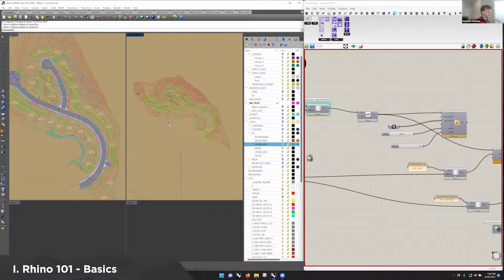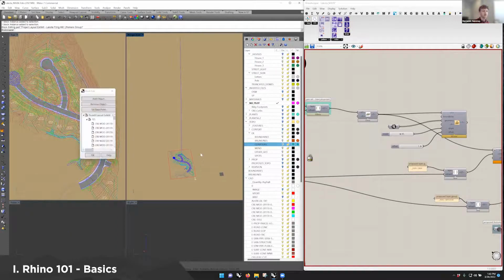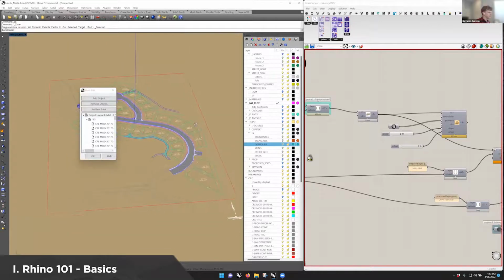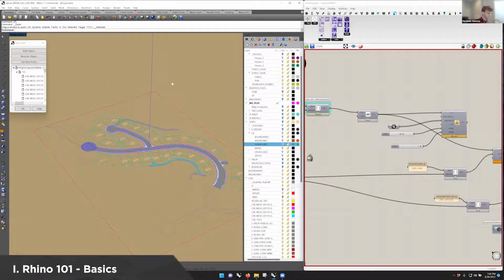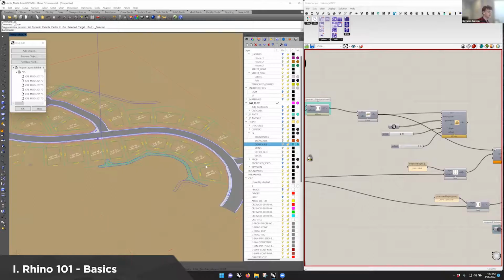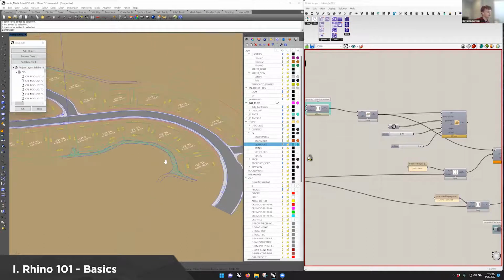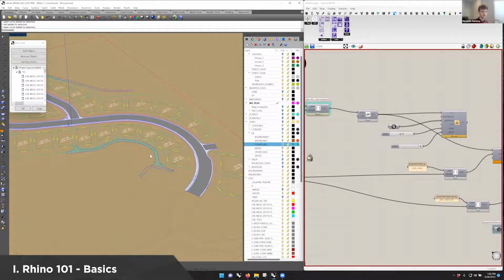Okay, so a couple more things to remember, especially when you start dealing with the plan down below. This will be a little more apparent once we talk more about the collage and the areas, but I'll go down here so you can see a little closer. Oftentimes when surveys or line work come in from some source, GIS or otherwise, the line work is not always perfectly touching or matching. And when you start creating surfaces and splitting them into different areas, whether or not the lines are actually joined or touching will make a big difference.